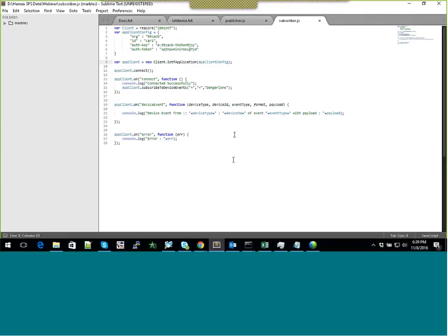Right now, the only thing on the cloud is your IoT service, which is the broker, and the publisher and subscriber are both local. The way he's connecting to the cloud is, since he's using the IBM IoTF library, all of that is already embedded. All of this communication is happening over MQTT.